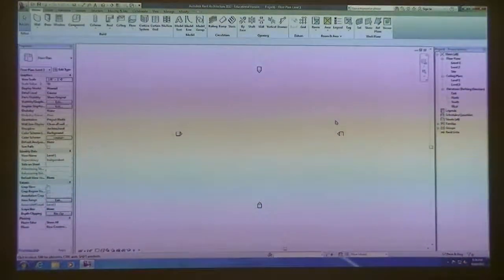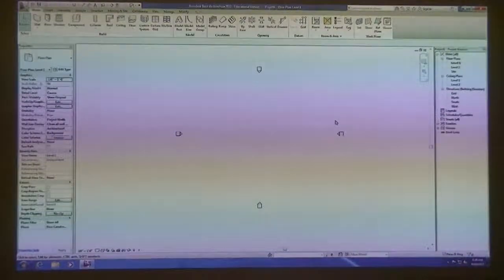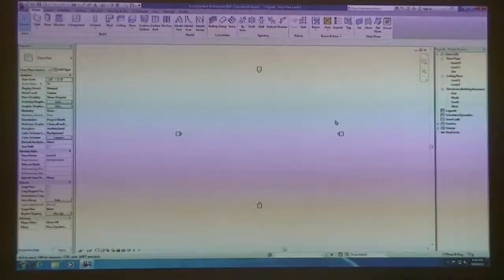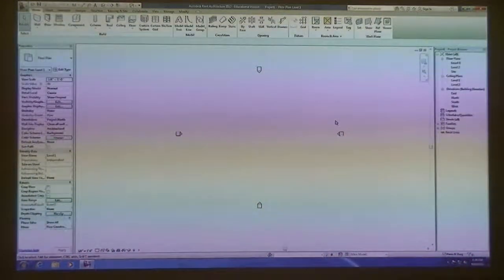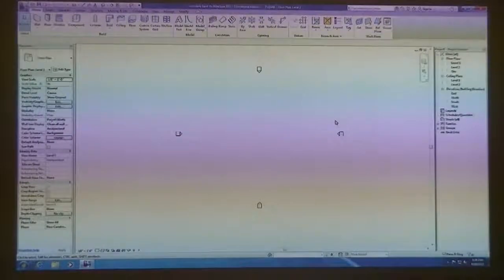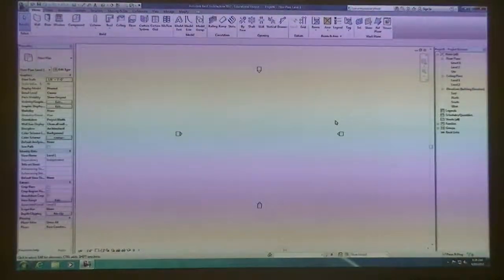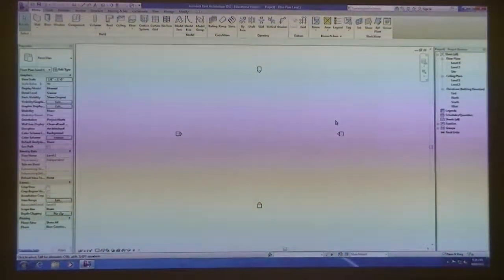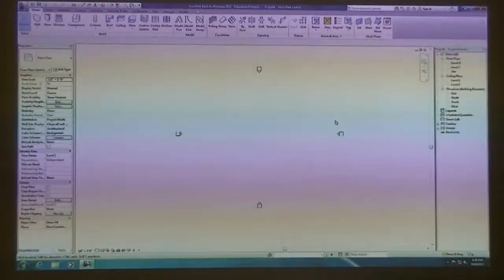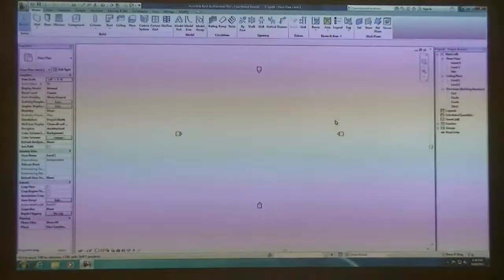One thing with modeling, whether you're in Revit or any other 3D program, what really makes your model, especially when you get into renderings and presentation views, is having that particular set of real details put into the model, whether it's how you apply your textures and materials, but also the details of actually showing guardrails at the appropriate scale, 3 foot 6 inches above a floor, and also showing the tectonic structure of that rail, so you're looking at the horizontal railings or the vertical posts or whatever the design might be.